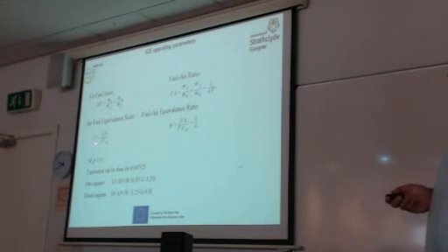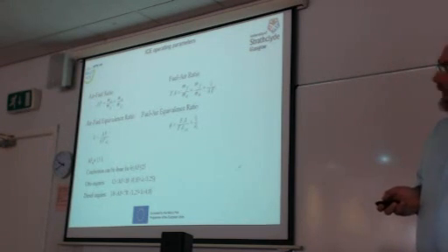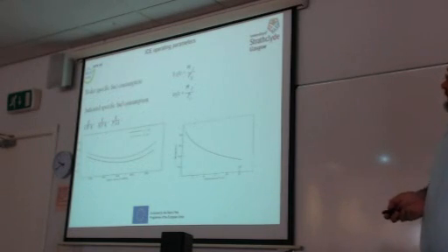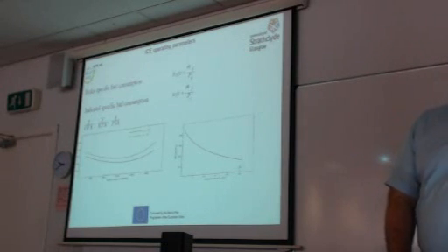In dual fuel engines, lambda is an important parameter, and we'll see later in some diagrams that there is a lambda window, an operating window, in which the engine needs to operate, and the manufacturer has to ensure that the engine will operate in this window. So it's a very important parameter. And then brake specific fuel consumption, which means grams of fuel per kilowatt hour of energy, or per horsepower hour. Usually grams per kilowatt hour is used.